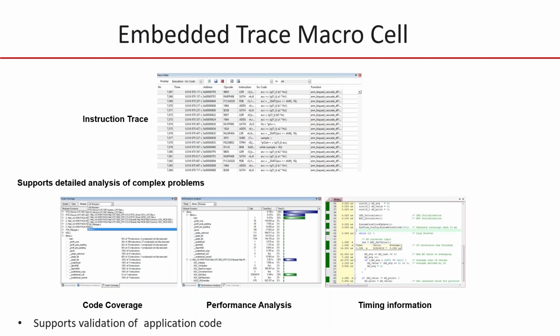And this is mainly because the way that the GPIO pins have been implemented by manufacturers, they're simply not fast enough to support the instruction trace. So you need to do a bit of investigation when you're selecting a device if trace is very important to you.